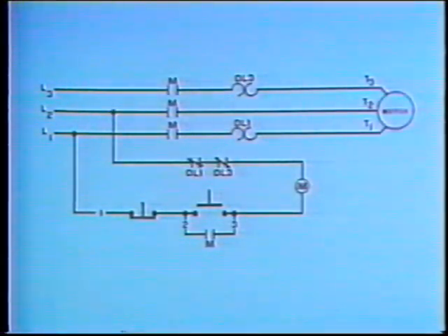Schematic diagrams are useful tools for troubleshooting controllers. A controller schematic diagram shows the controller components and how they are electrically connected. From the schematic, you can familiarize yourself with the components of both the motor and the control circuits and how each circuit operates. But a schematic diagram does not necessarily show the physical location of the controller's components.